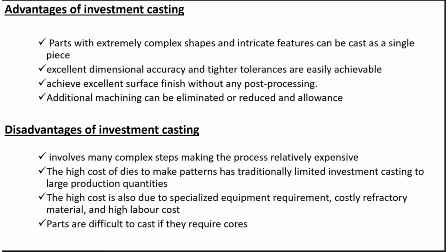Let's have a look at the advantages and disadvantages of investment casting. Investment casting allows parts with extremely complex shapes or complex geometries to be cast as a single piece. Secondly, since the pattern is made of wax, it has excellent dimensional accuracy, and tighter tolerances can also be easily achieved with investment casting.